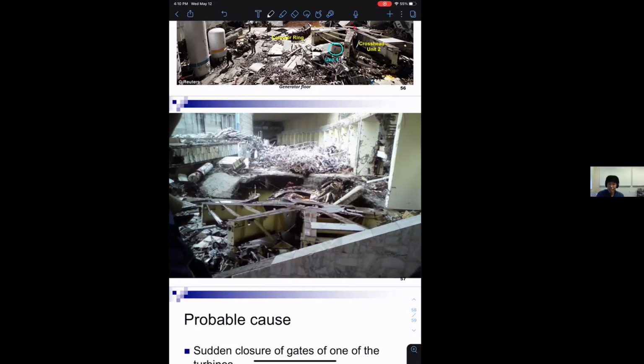because people are very conservative when we operate a synchronous generator, and want to stay far away from the stability limit. And typically people will question you, why don't you just operate a little bit closer to your safety limit? Why is it that important to stay below it? There's a picture of what happens when your stability goes wrong. When your control goes wrong, very bad things happen. Right? So for large power plants.